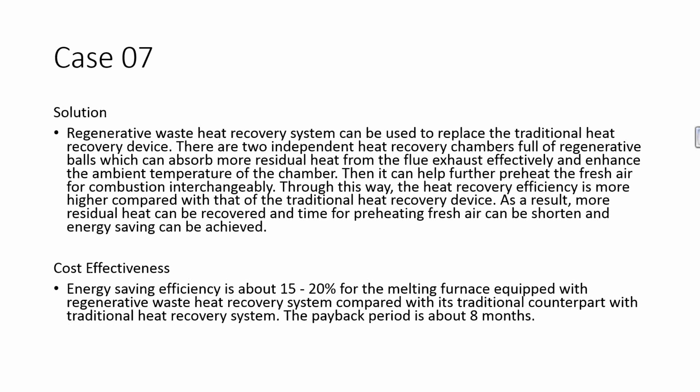The solution for this: regenerative waste heat recovery system can be used to replace the traditional heat recovery device. There are two independent heat recovery chambers full of regenerative balls which can absorb more residual heat from the flue exhaust effectively and enhance the ambient temperature of the chamber. Then it can help further preheat the fresh air for combustion interchangeably.